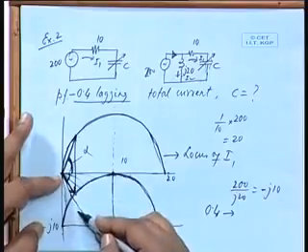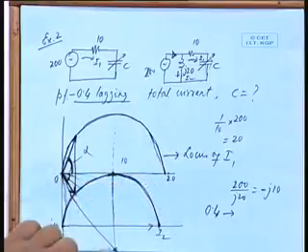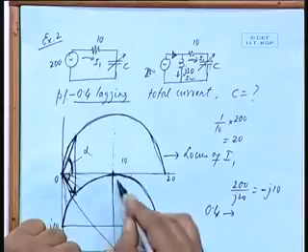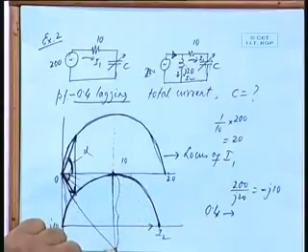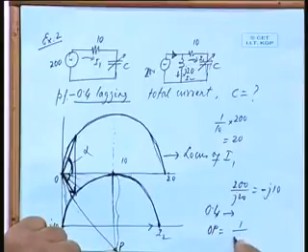Corresponding to z, it will be minus alpha. At minus alpha you draw a line, that will give you the corresponding reactance, 10 plus jx. Once you get this height, that is 1 by omega c. Suppose this is P, then OP is 1 by omega c. So, you know the desired C, is that all right?